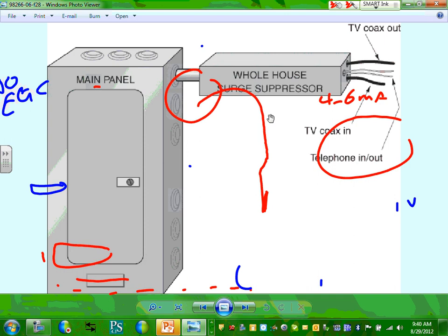On an engineered 3-phase, 480/208 project, a lot of engineering firms require a surge protective device in the main panel. It comes built into the panel, so when you buy it from Square D, Cutler-Hammer, GE or Siemens, they build it in per your specification. Cool? That's what they do to protect the whole system.